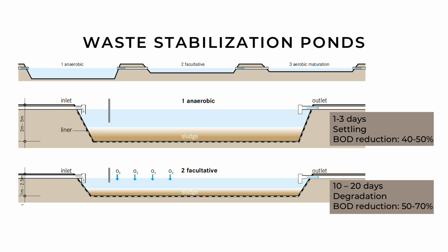The facultative ponds are shallower, constructed to a depth of 1 to 2.5 meters. They require a retention time of 10 to 20 days, which makes them larger than the anaerobic ponds. This is where the aerobic microorganisms degrade the suspended and dissolved matter, reaching a BOD reduction of 50 to 70%.